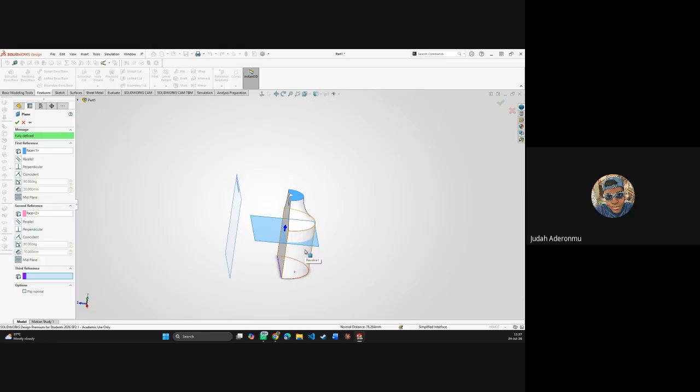Okay, when I'm trying to do my revolve cut, I've drawn the place I want to cut from. Can you show how to do a revolve cut again? I've drawn a rectangle to cut it, but I'm not able to select my axis of revolution. The axis I used to draw the bottle, I select that as my axis of revolution, and it gives a rebuild error: unable to create this feature because it will result in a zero thickness geometry. Okay, I'm coming here first.